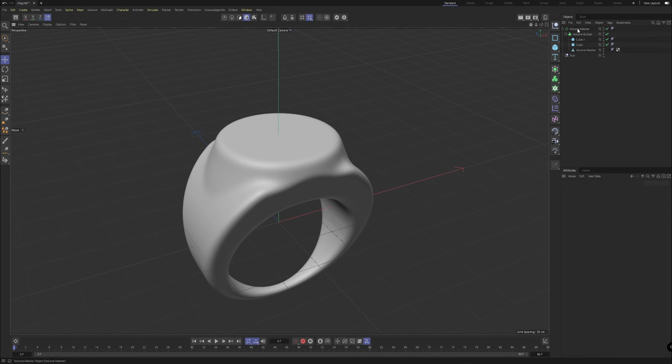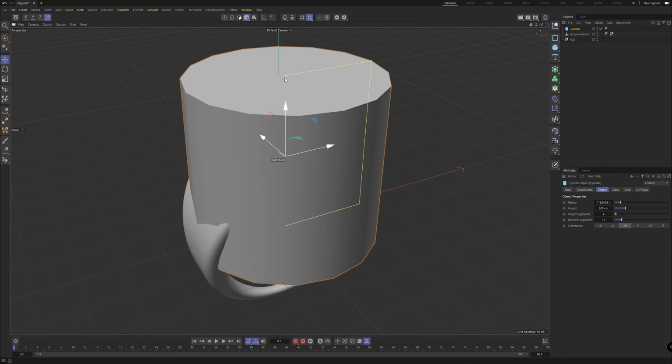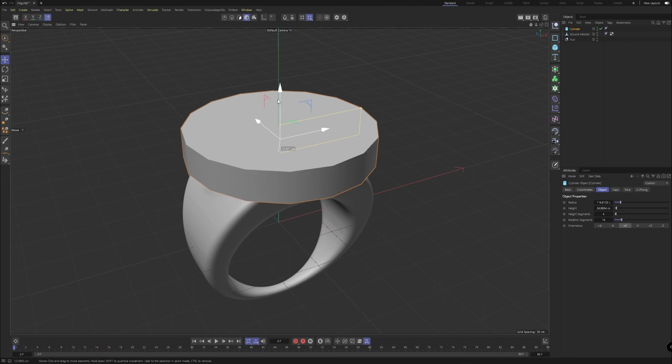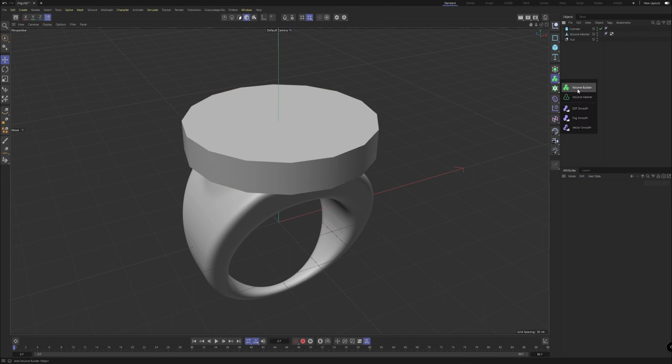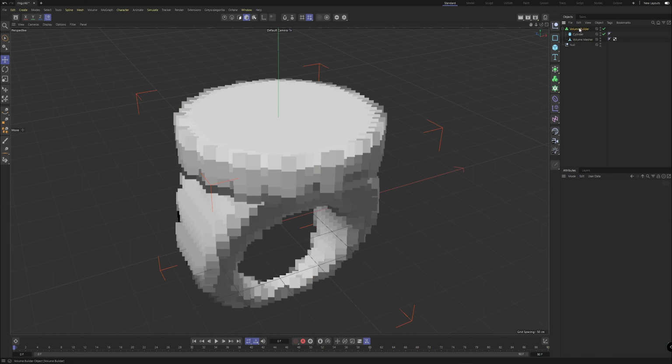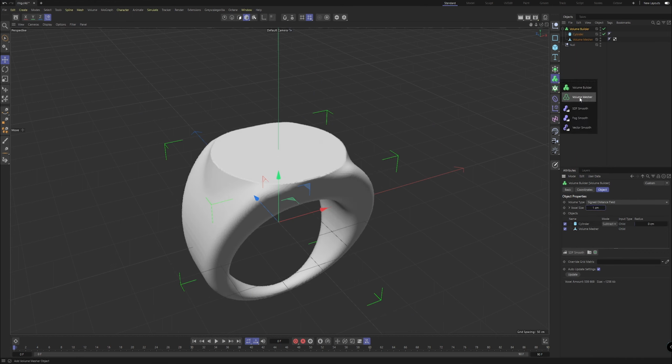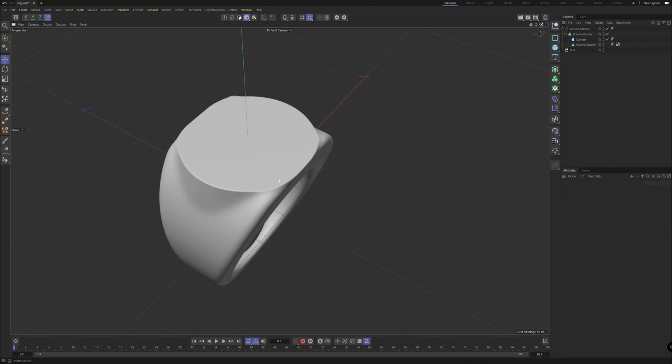So now we'll bake this one last time, and we will create a flat surface on the top. So we've already got a flat surface there, but we need it to be a little closer to the rim itself. So if we take a cylinder one more time, scale this down to something like this, and see what this looks like inside the volume builder. We can grab these two in, take our cylinder, I'll set that to subtract, voxel size 1, plug that into a mesher, and we're getting a pretty good circular look here.